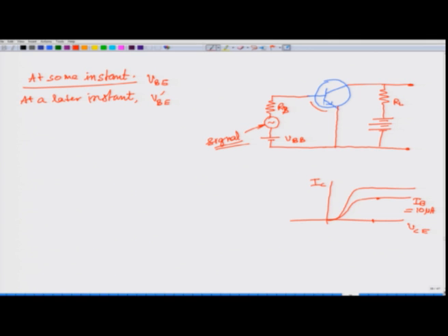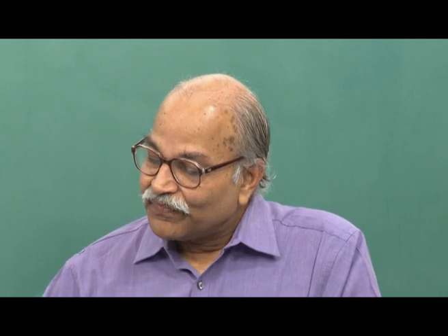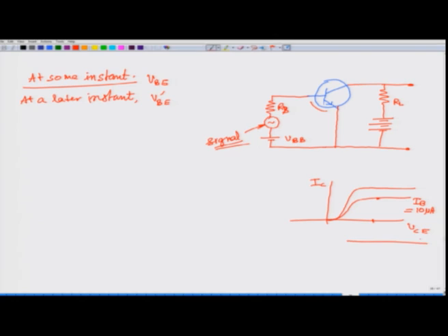If this biasing voltage has increased, you will have larger forward current, you have more injection of those charge carriers from emitter to base. But remember the collector is ready to receive them, it is very well reverse biased, and therefore the collector current will increase. And where will it go? Just using this output characteristics you can determine.